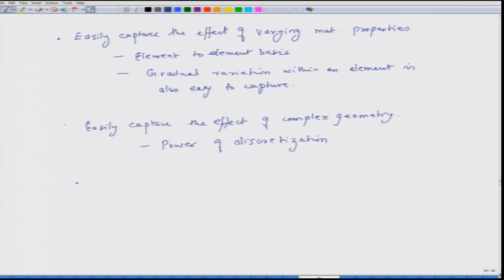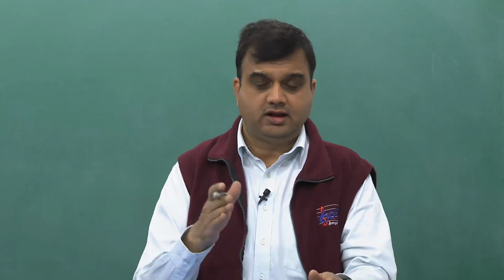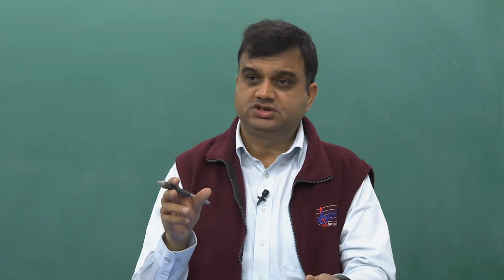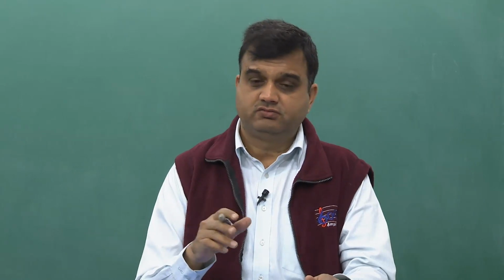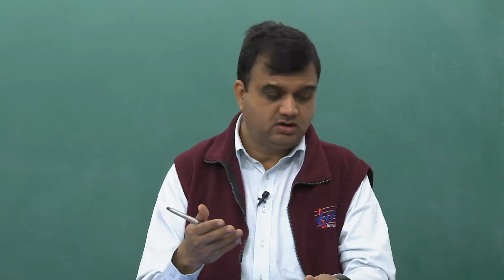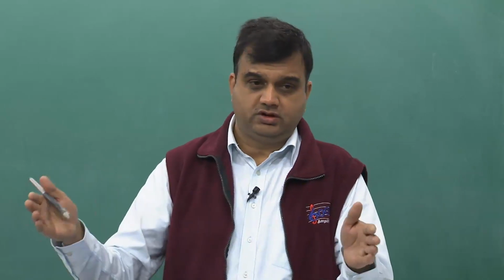The third thing I wanted to mention is the overall scheme and philosophy: we develop an equilibrium equation, and then we discretize the geometry on an element by element basis. For each element we assume some shape functions or polynomial functions which help us explain how the dependent variable, the variable whose values we want to find, varies over the domain of the element.